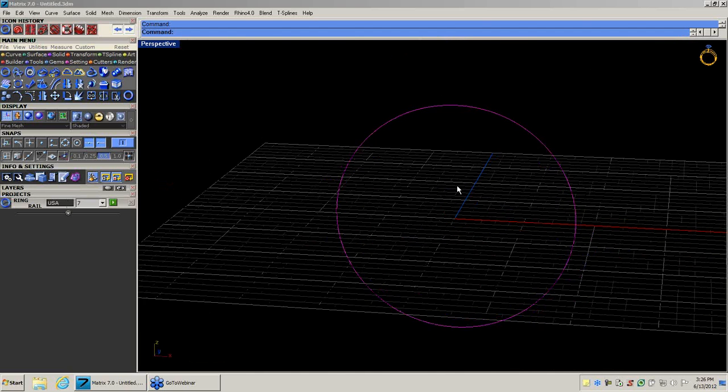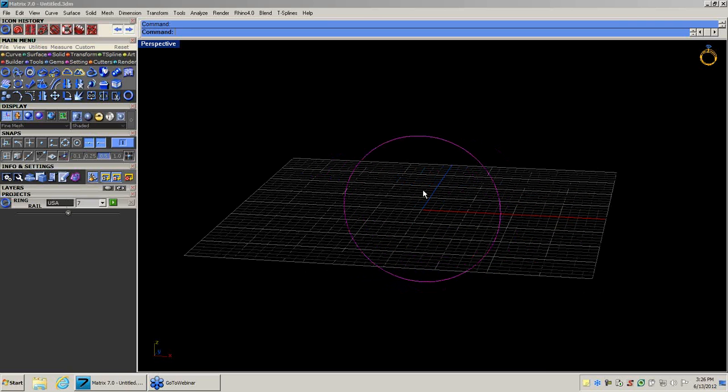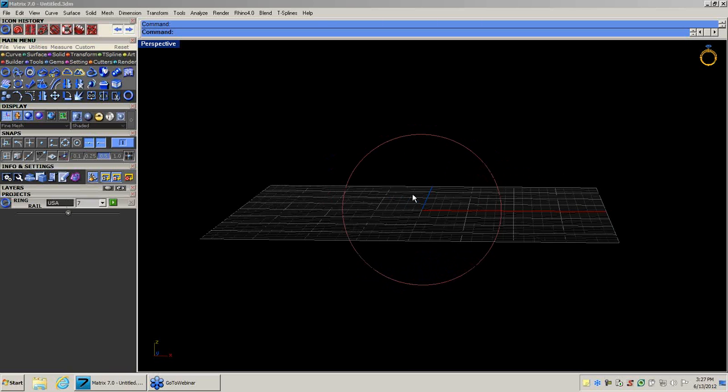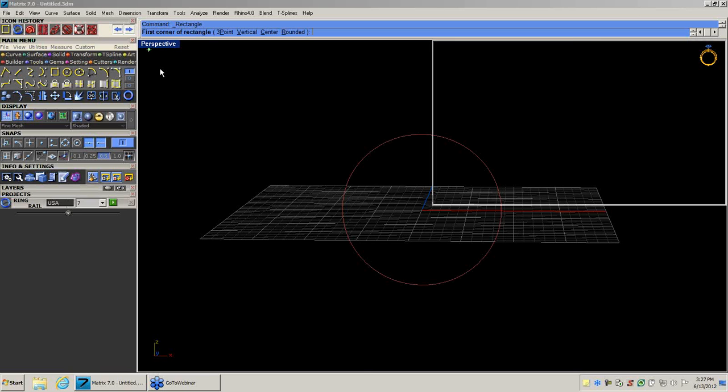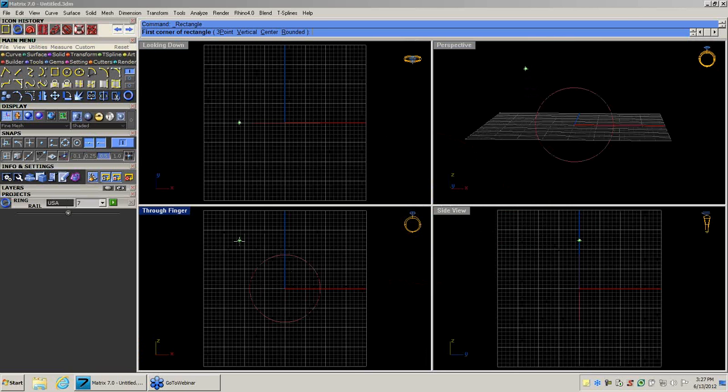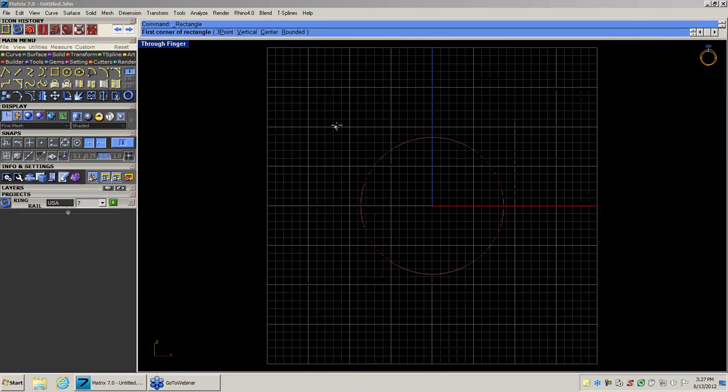If I didn't have this builder in here, if I was using just Rhino as a standalone system, I would have to know the circumference of this finger size, figure that out, divide it by pi, and then figure out the radius from there. We do it with a click of a button. Now, personally, I like to work inside of a constraint, is what I call it. So if I went to the yellow section over here, the curve section, as an example, and wanted to build a square ring, I might come in here and draw a square around the outside of my finger hole.